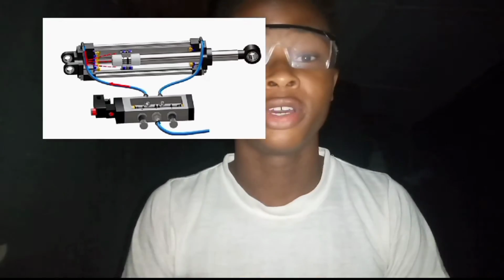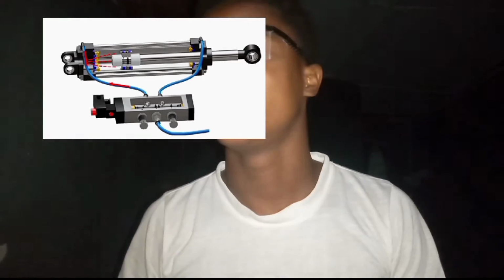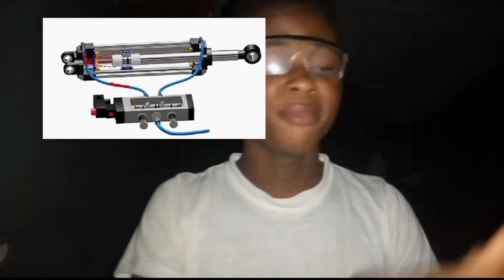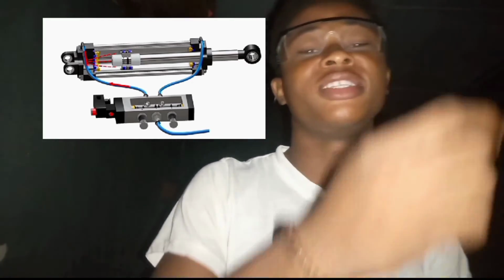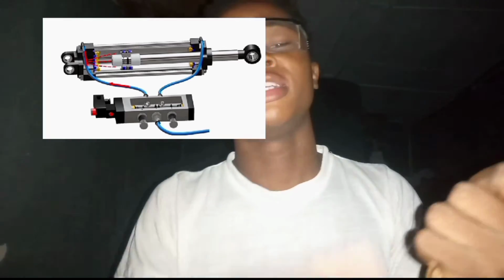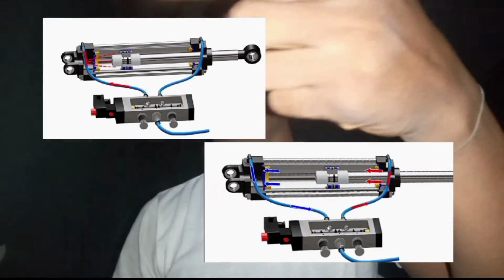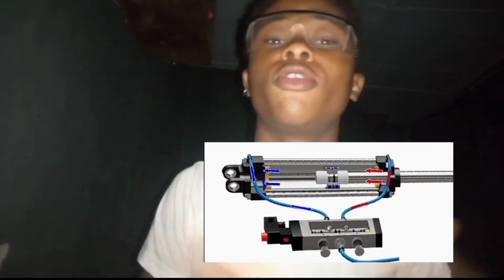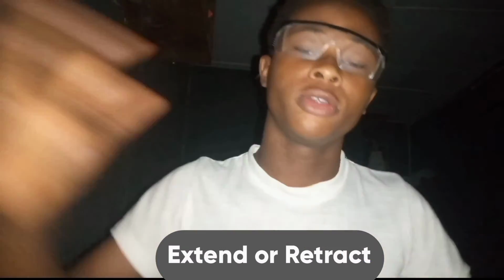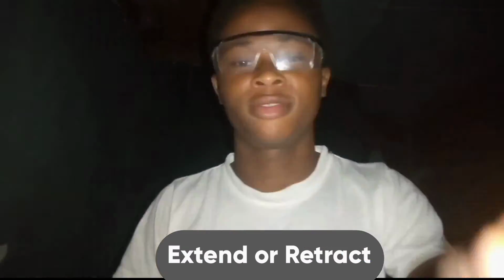Or the pneumatic, what do you call it again? The pneumatic linear actuator. Now that's simple. We can call it a mechanical pneumatic actuator, because we have to press it with our hand. When we press it, it releases the air pressure and lets it pass through, which then goes to the actuator itself and makes it either contract, or when you press it again, open.